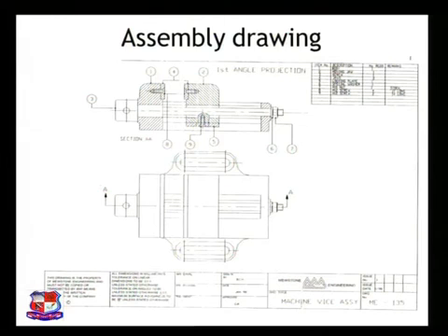This is one typical assembly drawing of a machine vice assembly. You can see here the number of components written over here. Number 1 is the body, which is in the part list or bill of material, and in the part list number 1 is written body, so this is the body. Number 2 is this one, that is a moving jaw. Number 3 is this one, which is a screw, it could be rotated. Number 4 is jaws, two jaws are there to provide proper clamping. Number 5 is a locking plate. With the help of this plate we can lock this assembly.